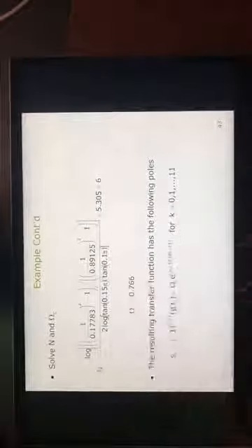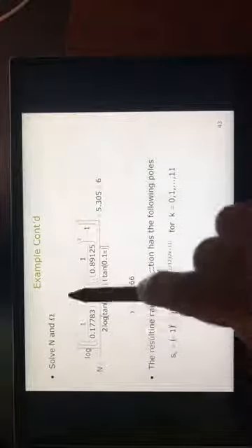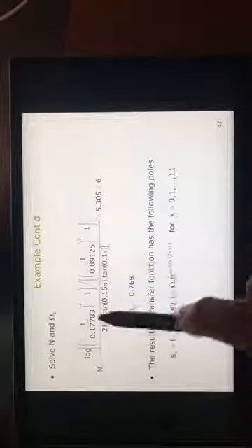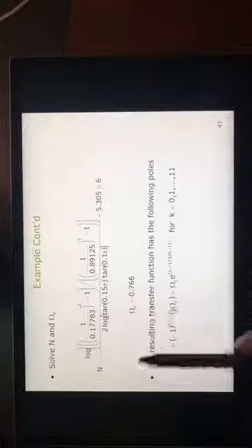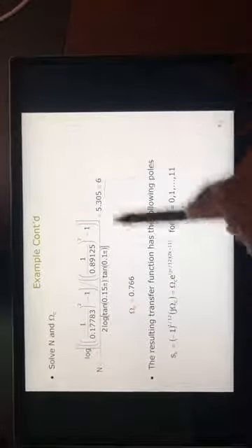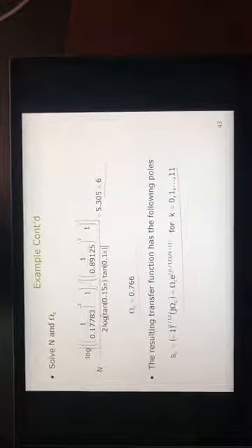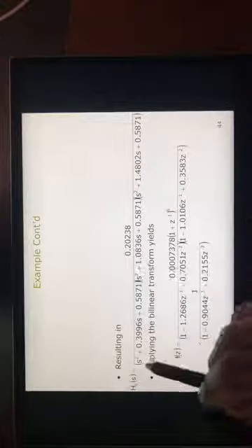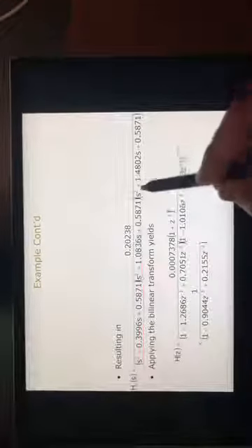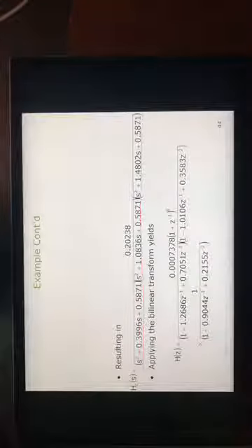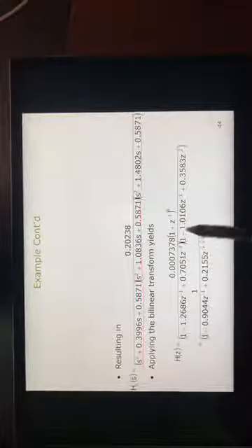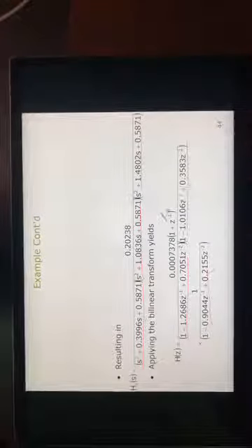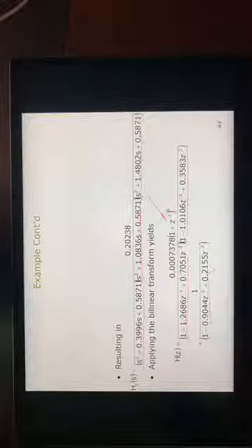Once you solve it, there are quite complicated substitutions which I'm not getting into, but you have these slides, so if somebody is interested, you can spend an hour or so actually solving these and finding out n, omega c, and then finding out all the 12 poles. Put half of them in the left hand side, so 6. So you find out that this is a transfer function, first second order section, second and third, and then replacing s with 1 minus z inverse over 1 plus z inverse will convert them into these. So you have an H of z, and you're done with this.